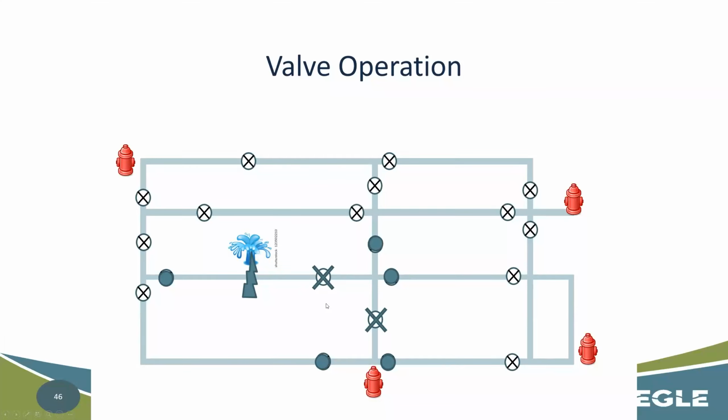The other piece of this is, here you are trying to handle this in a short amount of time so you can minimize the impact from this water leak. If you were able to just close two valves, that's a heck of a lot less time than if you have to close 1, 2, 3, 4, 5, 6, 7 valves effectually to get there, right? Especially because these two valves, I guarantee you're dinking around with them, trying to figure out, why won't it close? What's going on? I can't seem to get this thing to seal up, and before you move on to other ones, right? So this is going to cost you a lot of extra time that you wouldn't have had to spend if you'd had a proper valve turning program and had identified that these were an issue.